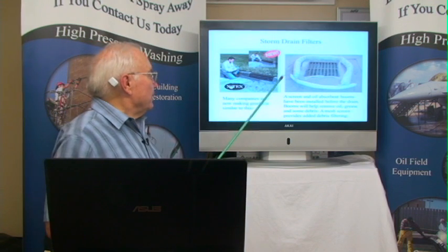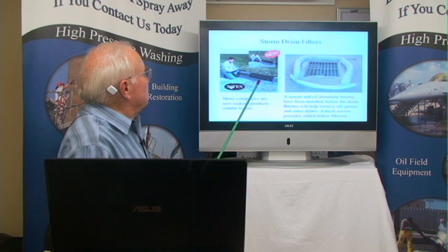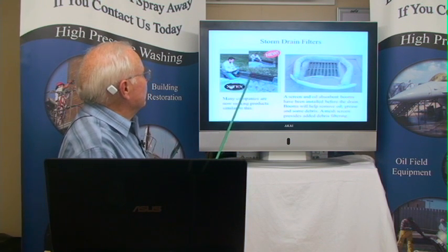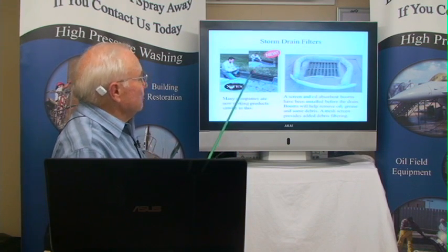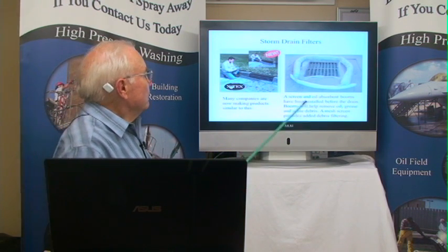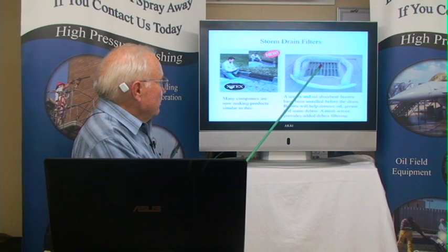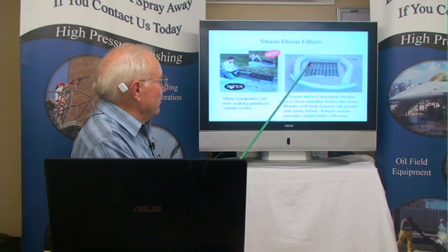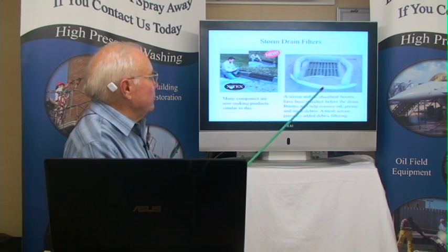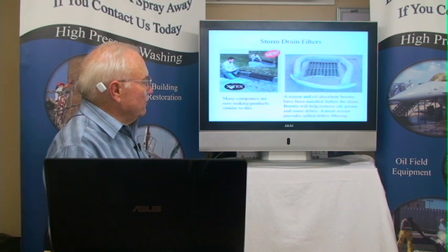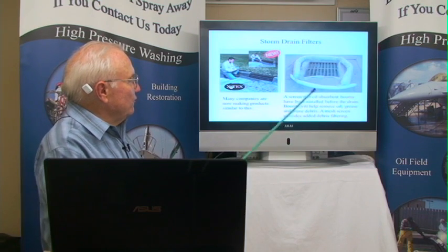I just have several examples here. This is another one made by another company, and they're putting down a filtration in front of the storm drain. You might be able to adapt this type of technology for your cold water washing with no chemicals. And here's another case where the contractor picked up the storm drain and put a screen under it, and then he put his filtration out here. So he did his always filter and always pre-clean. So there's his two filter methods.